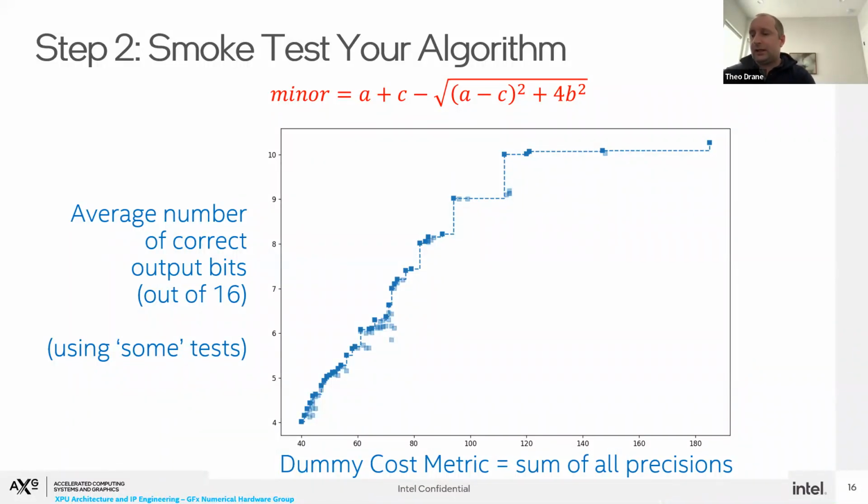What that means is, if I take a particular set of precision assignments and shrink one of those by 1 bit, then of course I expect the resultant hardware to be less expensive to build. So we have an ordering, and at this stage all we care about is the ordering. So we can simulate FPCores with lots of different precisions and create this Pareto frontier.